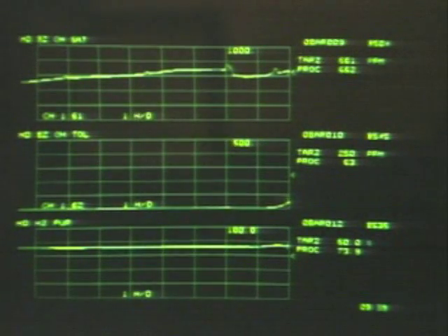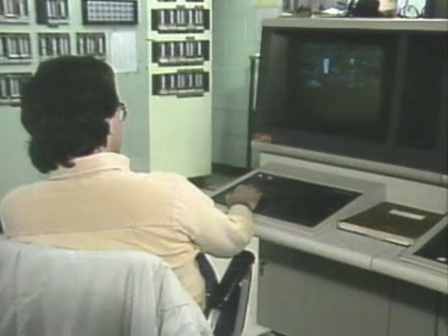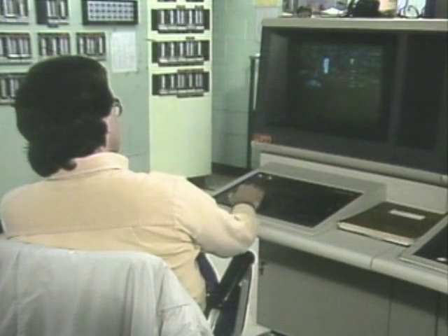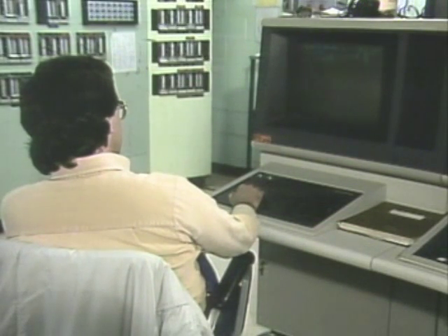Direct composition measurements are analyses that allow personnel to directly observe the percentages of components contained in a product. One type of instrument that is commonly used to perform direct composition measurements is a process chromatograph. A process chromatograph analyzes a product and provides a readout of the component percentages. The measurements made by the chromatograph can be compared against specs to see if any adjustments are needed to ensure that the product meets specifications.